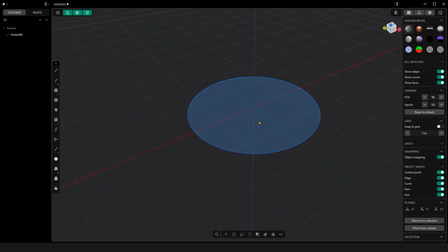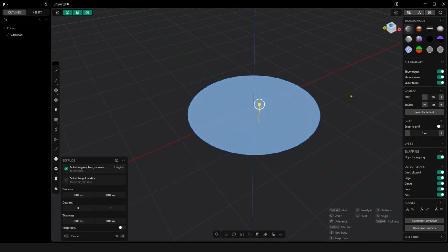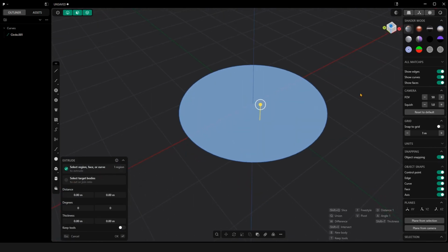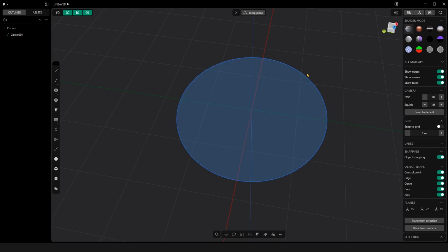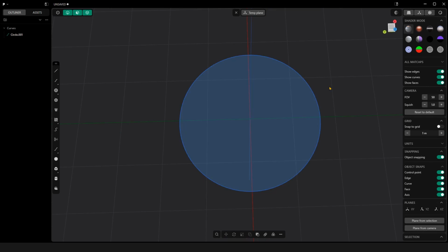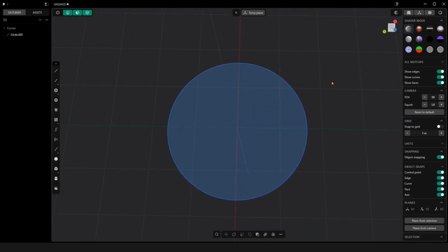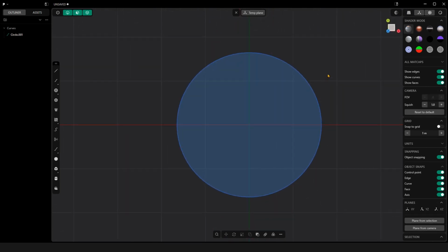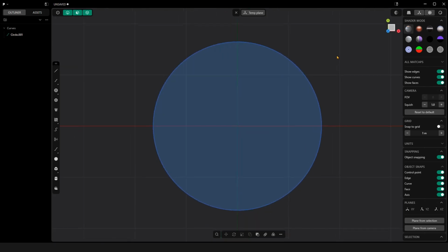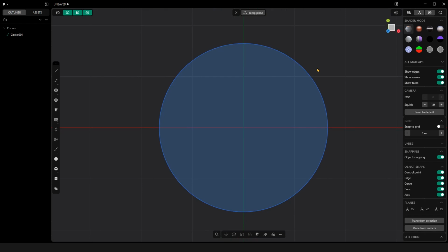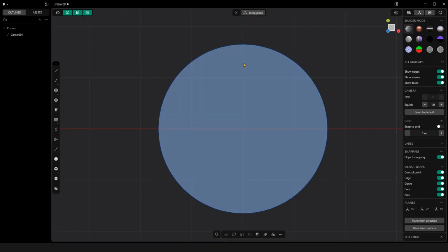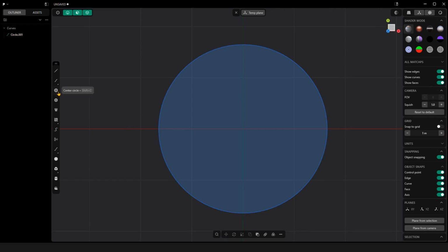And so what I want to do again is select it, and for me, I'm using Blender hotkeys. I'm going to hold Shift and then Space, and what that will do is make sure that the working plane is according to this shape here. All right. And now if I hit spacebar, it's going to make sure that the viewpoint, the perspective, is snapped to that selection, right?